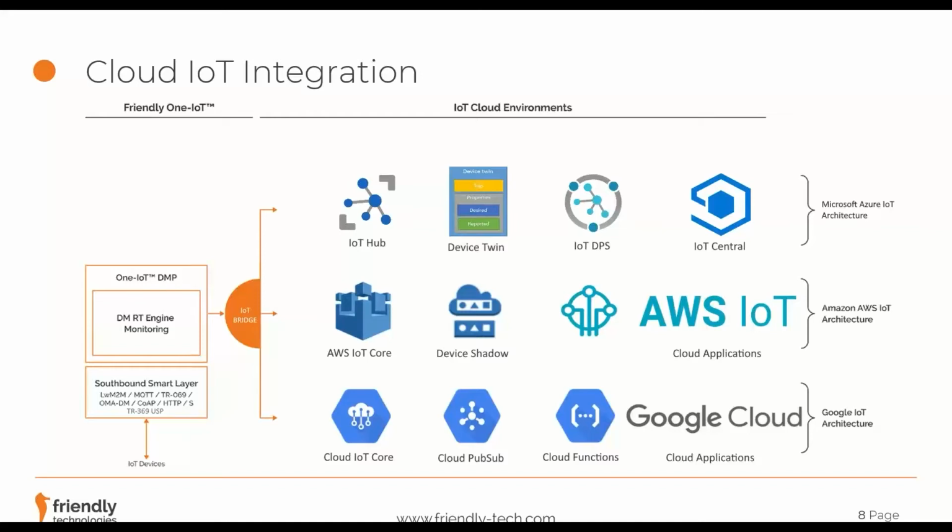Now, in the end-to-end integration there, we also create an entry into the device provisioning server, the DPS, and in addition, we create a device template in IoT Central. That device template defines the interfaces to the device and how to interact, whether you want to do a firmware update, reset the device, or control or update the device. So those templates created in IoT Central allow you, when you develop your application, to interact with that device.